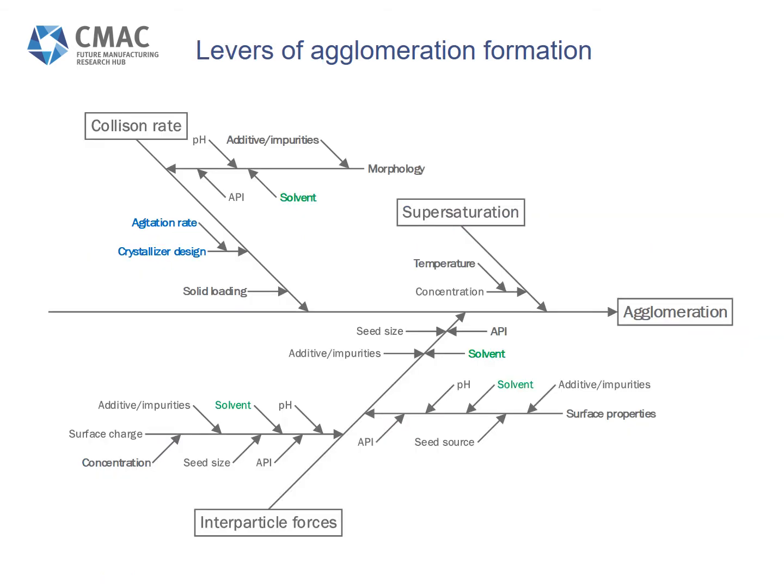Now based on this mechanism, we can identify the levers or process parameters which govern agglomerate formation. The work I'm going to talk about today will focus on interparticle forces through solvent selection and collision rate through crystallizer design and agitation rate.